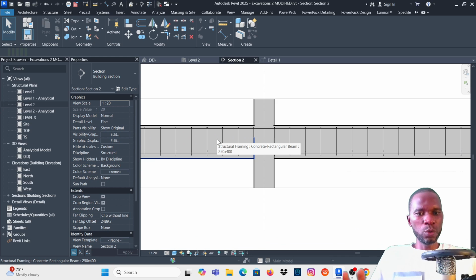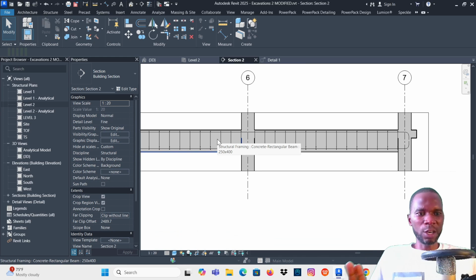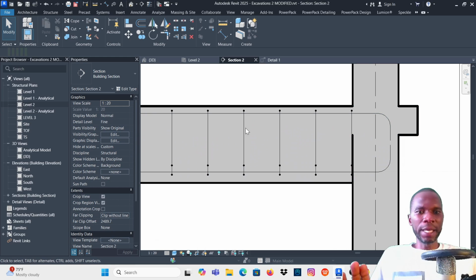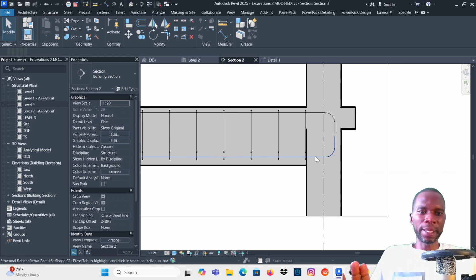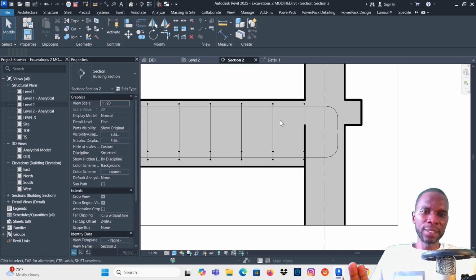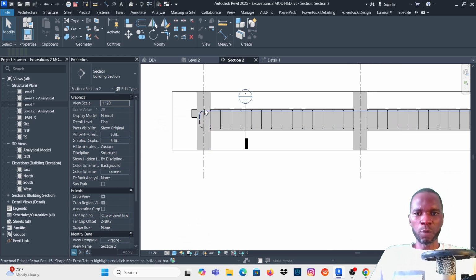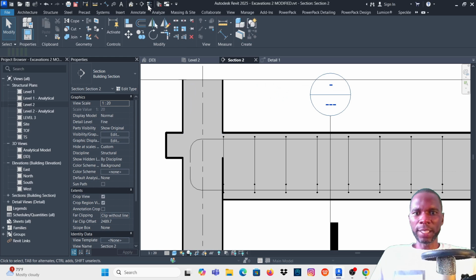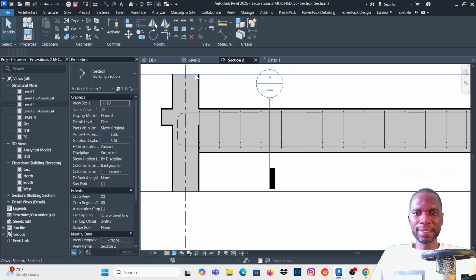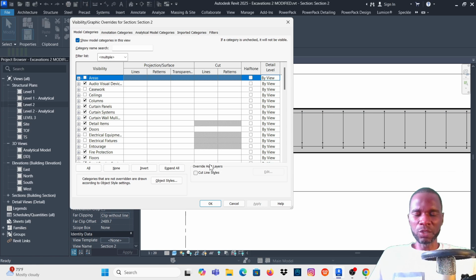So what I'm going to do is simply according to my preferences and in my region, but you can do whatever I want to do with what I want to show you in terms of customizing or making sure that, you know, the line weights, the thickness for the rebar is shown in the correct way. So what you need to do is to make sure that you activate this one. This is how it's going to be printed out. And now let's get started with, for me, I want the formwork, like for the reinforcement, to be very, very thin. So I'll just go to visibility graphics.